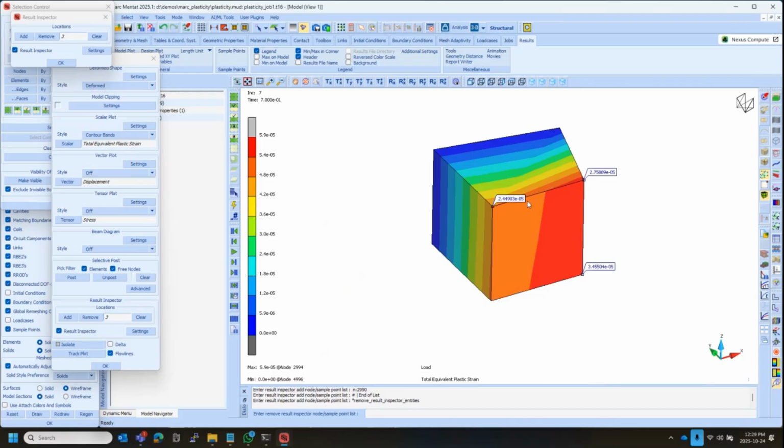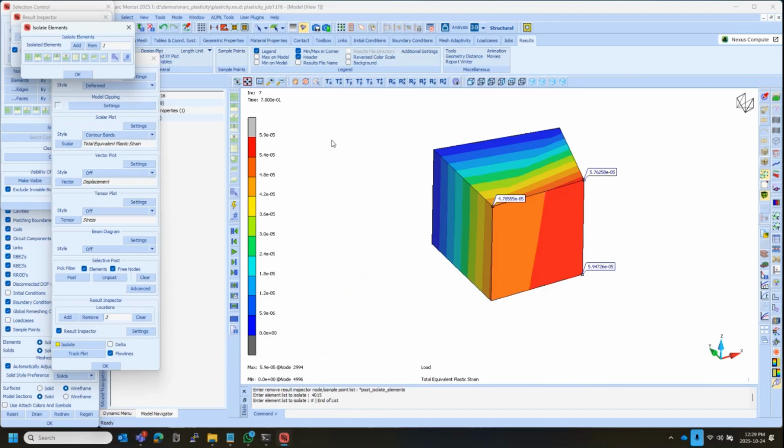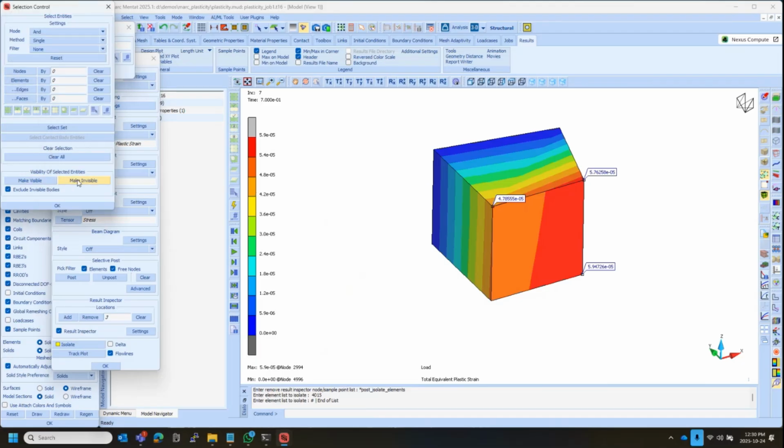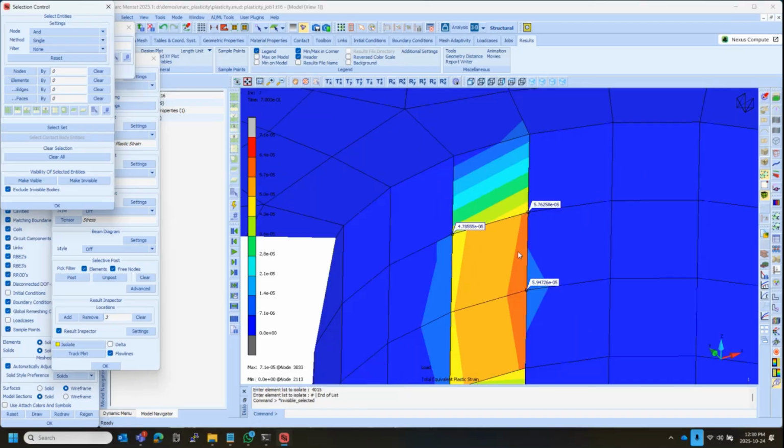So if I want to see just this element, this is what the isolate tool is about. I can say isolate this element, and now that number, that number and that one match exactly. What isolate says is average only the elements in this list together, and then everything next to it also separately average those. So even if I show the full model, it still shows the one element that I've got, that one's values, because these nodes, since I isolated it, are associated with this one.